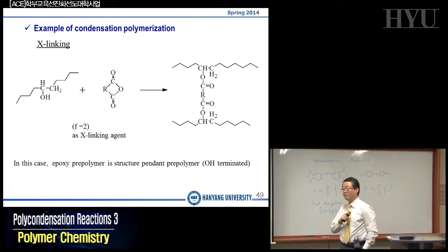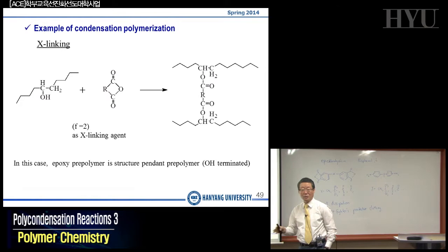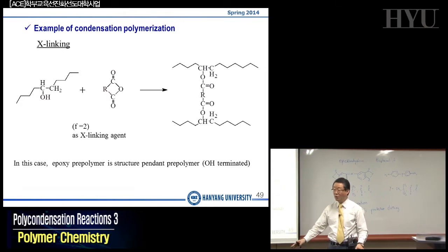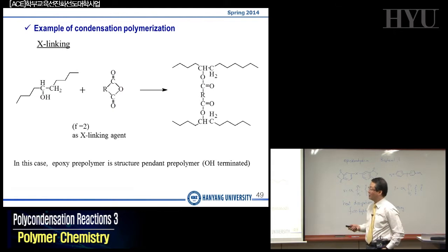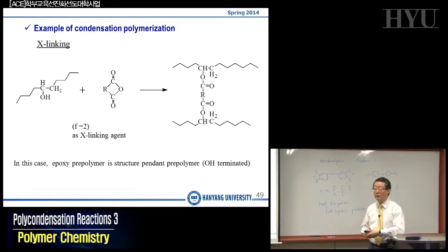If you look at the gas station or gasoline station, the floor has a little bit of a different color. Or if you look at the laboratory inside, the color is a little different. And if there is any chemical floating around, including gasoline, you have to protect your floor with a coating which has chemical resistance. Okay? So epoxy coating can be used for that purpose. Okay?